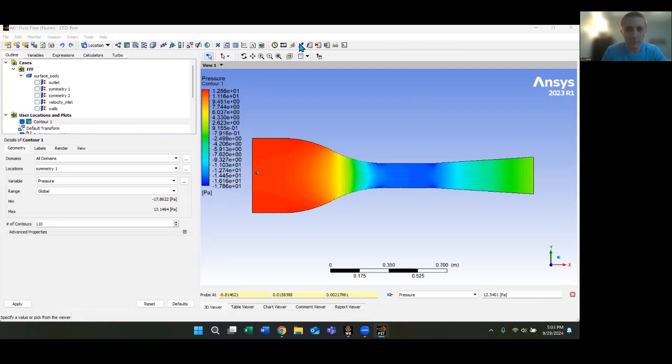All right, I was able to get the probe now. So we've got our probe. It is set here. There is our pressure. We've noted this down. And then we can move this here. We moved it into the settling chamber, and that's where we've got our negative gauge pressure here. So that looks a lot better than before. But we can move this probe around. We just need to keep it in the center away from the walls of each of these to get our pressure for both of those.